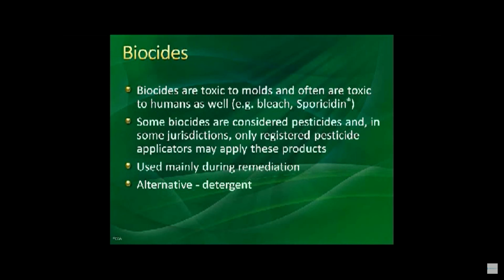And this is where we come into it. People have gotten into the habit of using biocides and antimicrobials. Sometimes the biocides are toxic to us. Some biocides are considered pesticides, and in some states you've got to be licensed, especially in areas like New York. Biocides are good to be used during remediation. There are alternatives. There are detergents that are recognized as a cleaning product to do mold remediations.